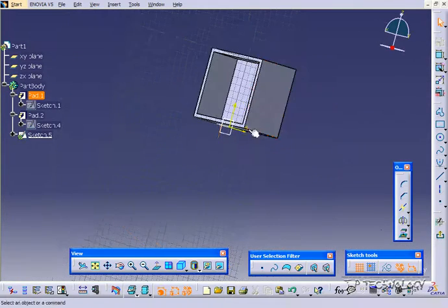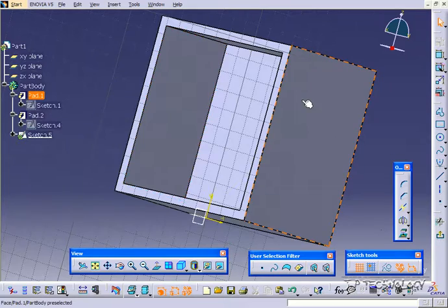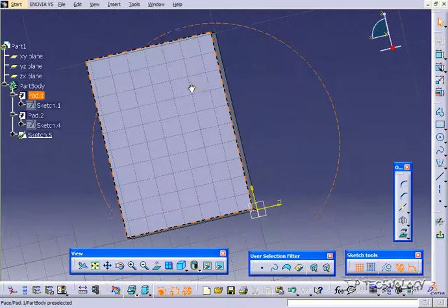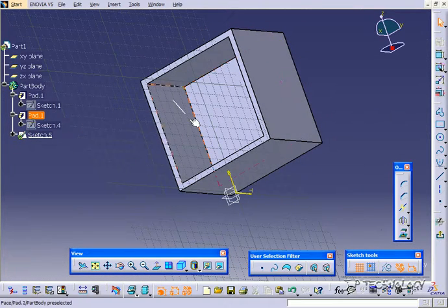Now when you're drawing these lines in here, there's two different ways to do it. You can go from line to line, touching the points there, or you can do it inside the box without touching any of the lines. So this is two different ways of making a stiffener. The first one we're going to make is just draw lines that are inside this box, not touching the edges. So let's just rotate it around a bit and just draw a little line just like that in there. And if you look on the side, you can see that it's inside the box.